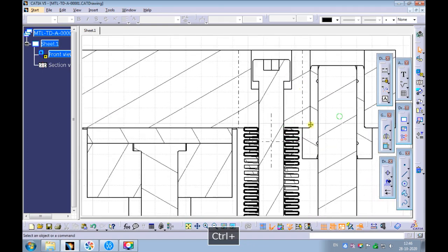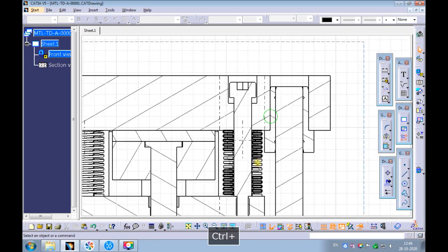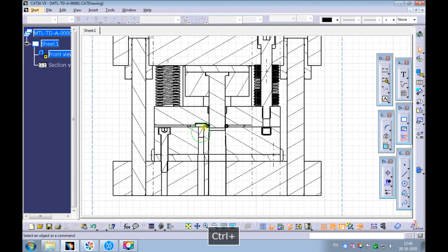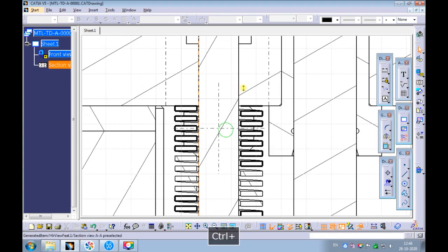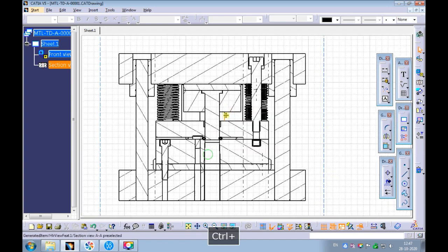Observe the position of the section profile is not on the parts. As you can see, all the parts are hatched, indicating the section cut. Also, observe the standard parts like the screw and shoulder bolts are also cut. It's a standard practice not to cut the standard parts in section views.